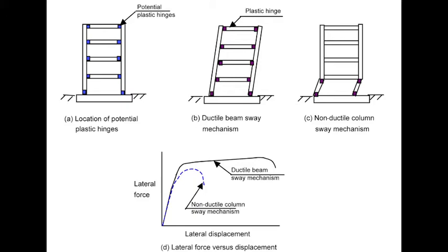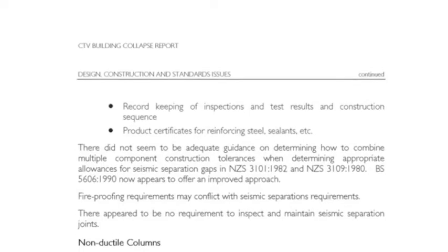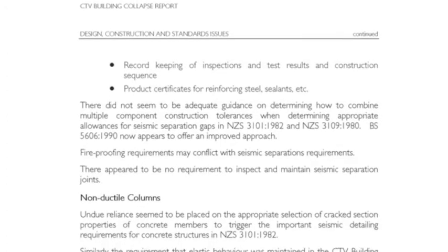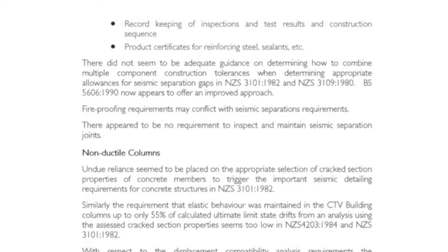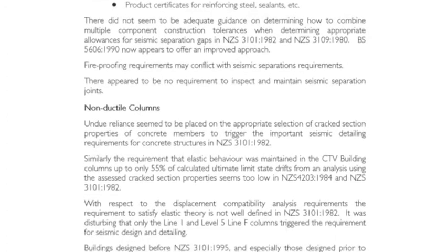Ductile reinforcement is when the buildings use plastic hinges along the edges of the structure, that when under stress, fail first, so that the damage is caused in a predetermined location. This is especially helpful in areas that are prone to earthquakes because there's constant movement, and buildings that are non-ductile will show no failure under stress until it's too much and they just crumble.